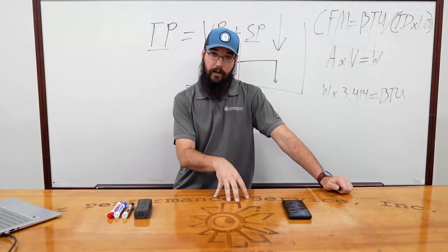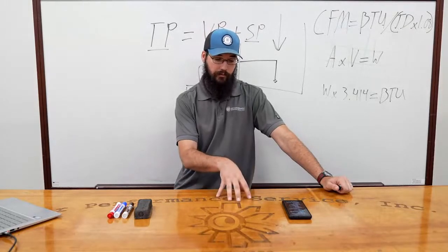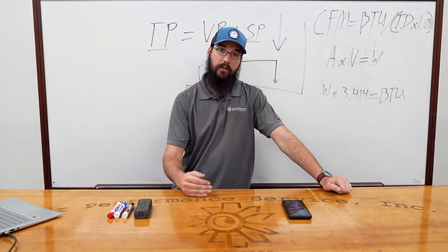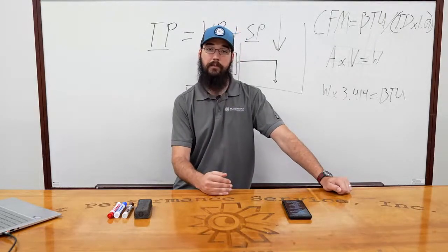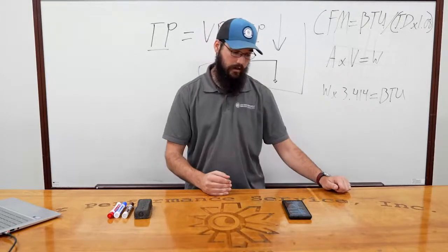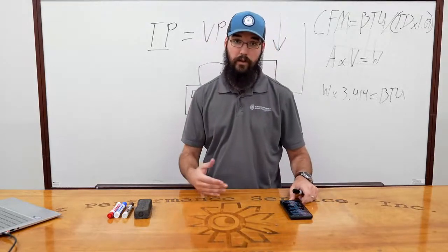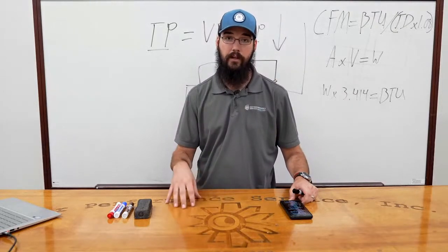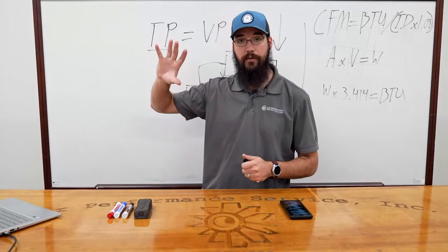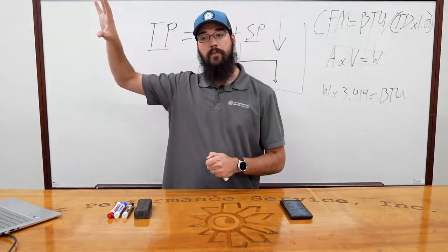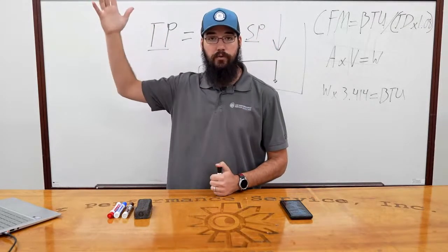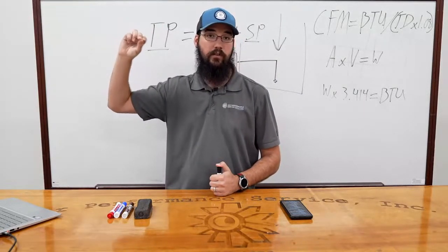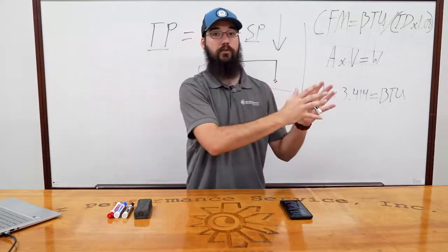You cut the airflow down, however you throttle it, then you end up seeing the superheat and the saturation come down together. And then the TXV gets to where it actually has throttling range, to where it can control the flow again, because what that high airflow did is it pushed the TXV so far that all it could do is open wide open and flow its maximum value. And it still wasn't enough because you're inputting so much heat.